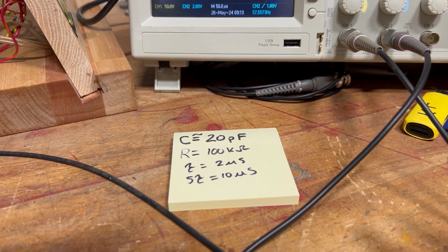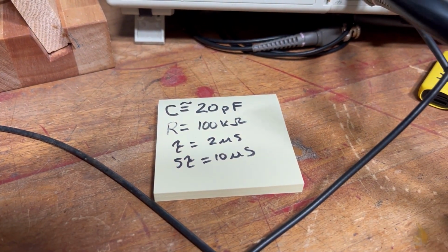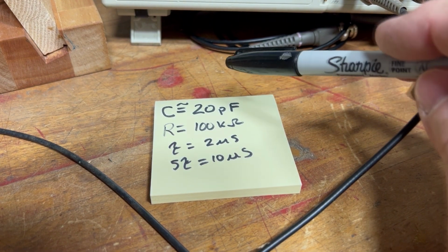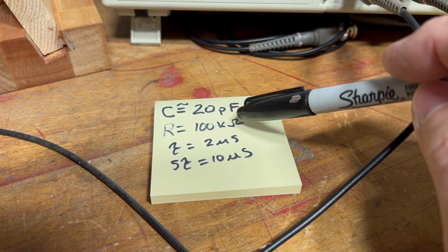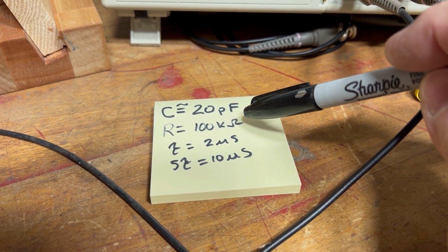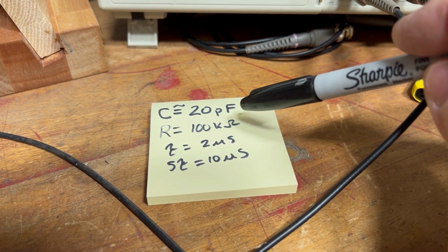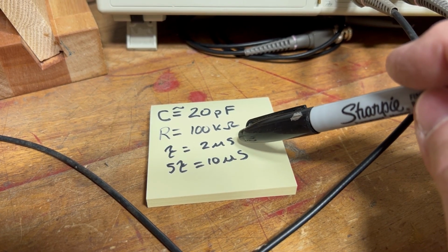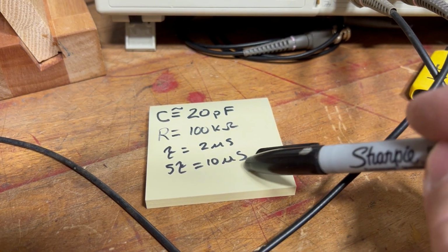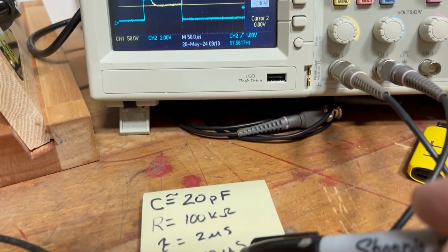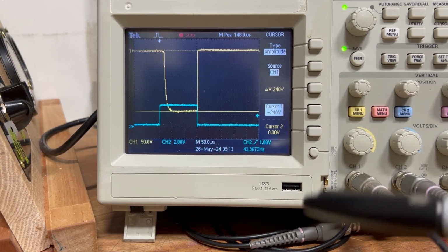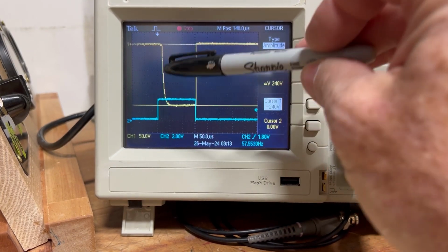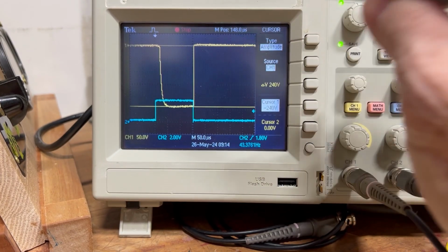The capacitance of any one of these bars to any other part of the circuit is nominally 20 picofarads, according to the data sheet, according to the patent information, of course. I'm driving this with a MOSFET and a 100k ohm resistor, so the effective resistance will depend on whether I'm in the on or off state, but the longest time constant would be 2 microseconds, and that old adage that everything's over after 5 time constants. So 10 microseconds would be sort of what I would expect for a curve, and if I look at this, it looks like it's about over after about maybe 20. No, that's about 50 microseconds, so maybe the capacitance is a little higher.